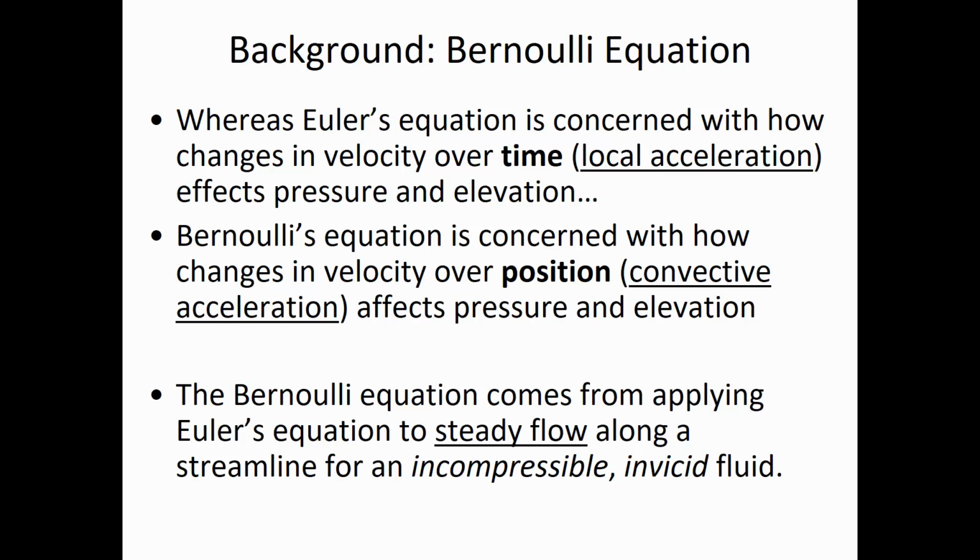Because what we're saying is the fluid has to be incompressible. Well, no fluid is perfectly incompressible. Even liquids can kind of be compressed a little bit. But liquids are a little bit better in terms of meeting the standard of incompressibility. But then we're saying also, this Bernoulli's equation should only be applied for fluids that don't have any viscosity. Now, gases are kind of good at that. I mean, they have very little viscosity, but they still have some. But the point is that Bernoulli's equation never really applies. And the reason why is it can't account for frictional losses.